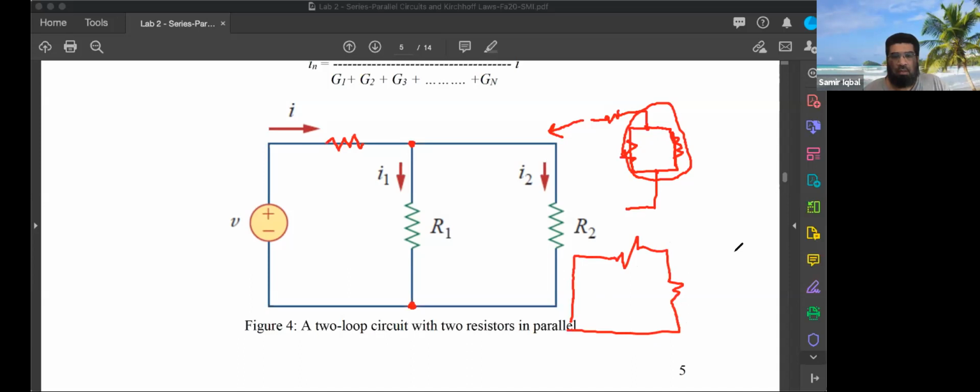Does it make sense? You have to visualize the two points between two resistances which create that small parallel circuit for you to solve. You'll solve that to find the equivalent resistance, and then find the equivalent resistance of that with any other resistances. All right.